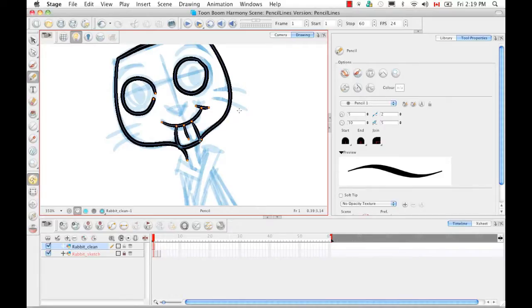So something like that. The next mode I'd like to talk to you about is the auto adjust thickness, which is this next button here. If we press that, you'll see that the color swatch here becomes enabled. What this option does is it allows you to pass your brush over a pencil line and thicken it by the number of strokes that you pass over that line. So as you can see, the width of this has increased.